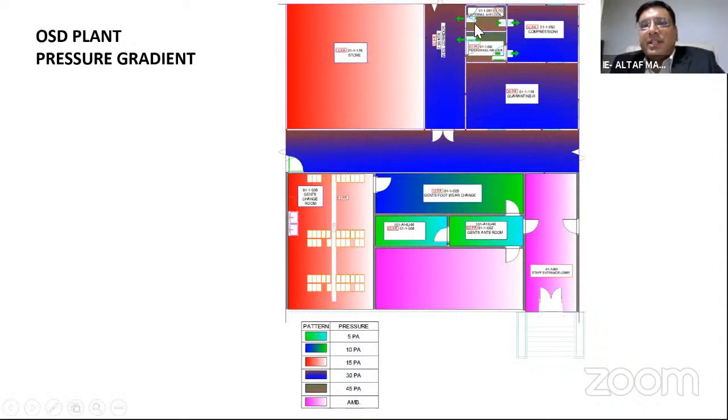You can see that these airlocks are acting as very positive. We generally use the terminology bubble airlock. The pressure from both airlocks moves to the corridor as well as the compression. This particular design will avoid cross contamination. No air from these production areas, process areas, will move to the main corridor, and it cannot go to the other process areas. This is very critical while designing any clean room. So in these cases, your production rooms are negative.